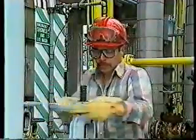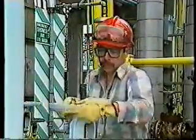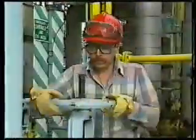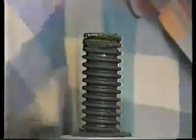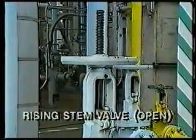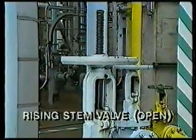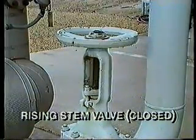The hand wheel turns freely but stays connected to the yoke. As the hand wheel is turned counterclockwise by pushing with the right hand and pulling with the left hand, the stem and attached gate rise and the valve opens. Turning the hand wheel in the opposite direction, or clockwise, closes the valve by lowering the stem and gate. Because of its design, this is called a rising stem valve. You can always tell if the gate is open or closed by looking at the position of the stem.